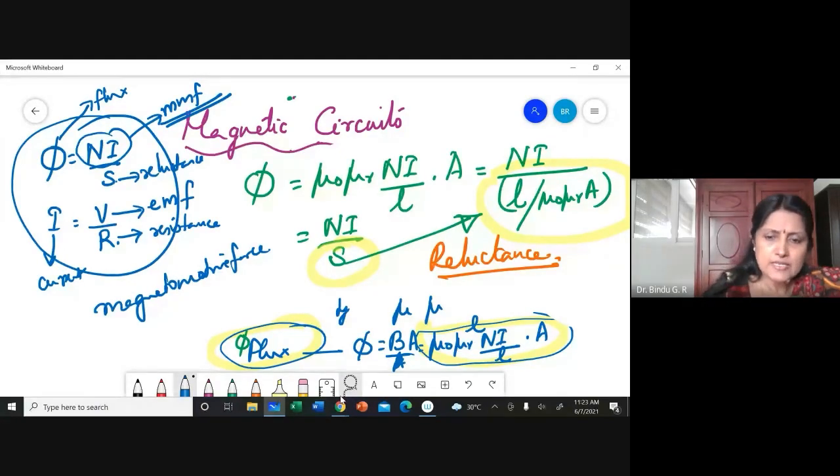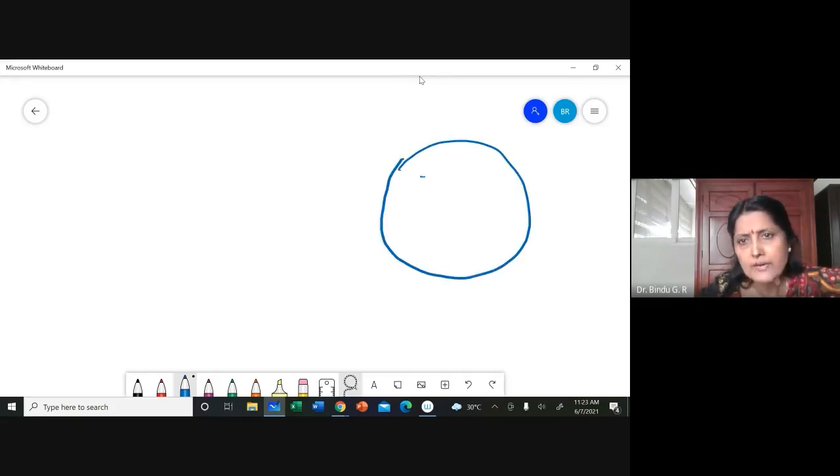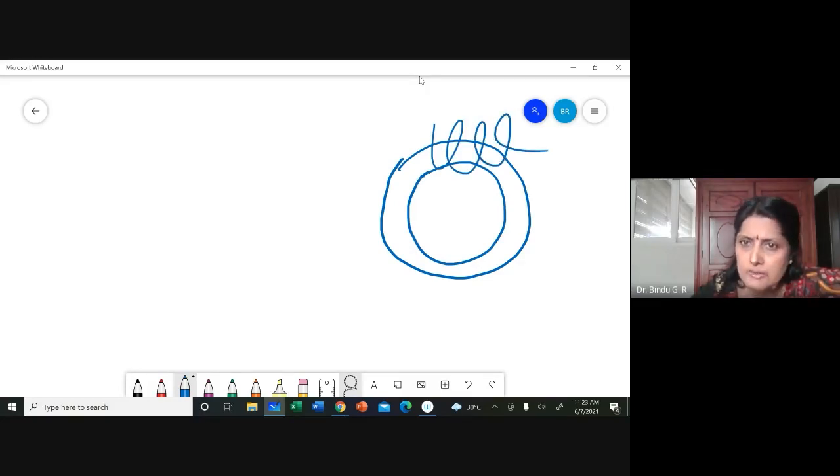Now, let me ask you why we have provided a toroid, a ring. Because the reluctance offered by a magnetic material like iron is much less than the reluctance offered by air. So what will happen is that more and more flux will be produced within the toroid.